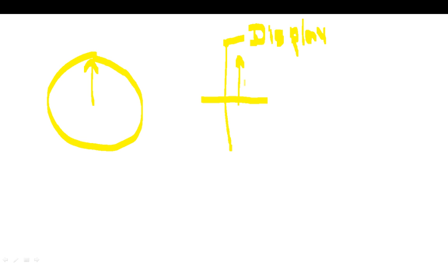And this is a pointer. So there is always some gap between dial and pointer. So if a user is not standing perpendicular or seeing perpendicular to the plane of this display, then what will happen?